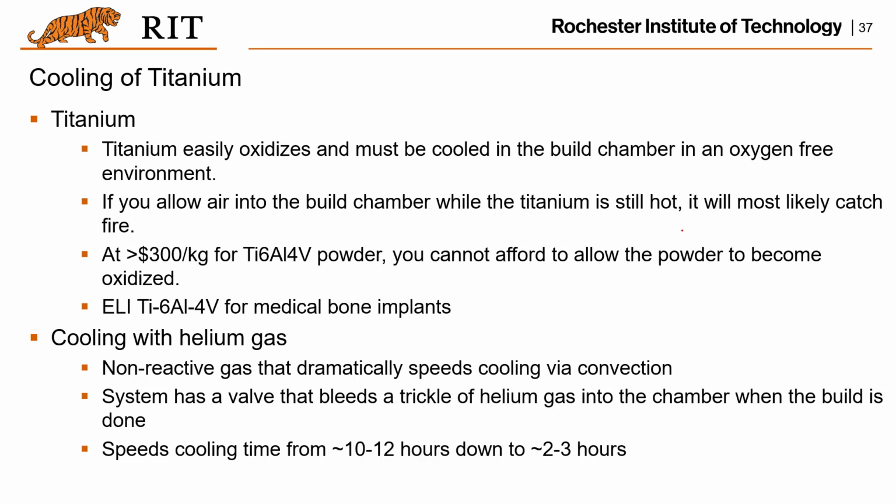For the cooling of titanium, it's very dangerous because it easily oxidizes, and that could cause an explosion or a fire if you do not cool it carefully. So first of all, you would like to either cool it in the vacuum or cool it in helium. If you cool the titanium with helium gas, it will speed up the cooling from 10 to 12 hours down to only 2 to 3 hours. Definitely you want a much faster cooling.